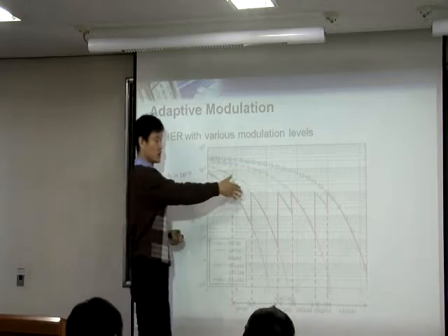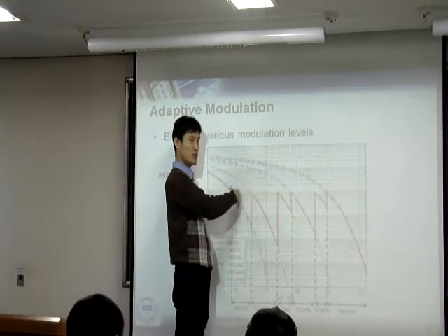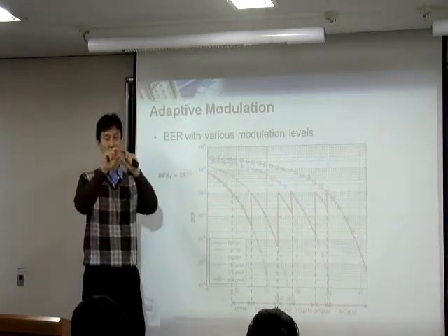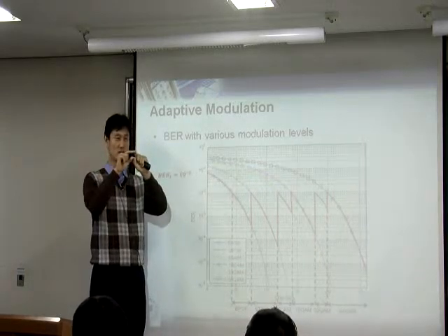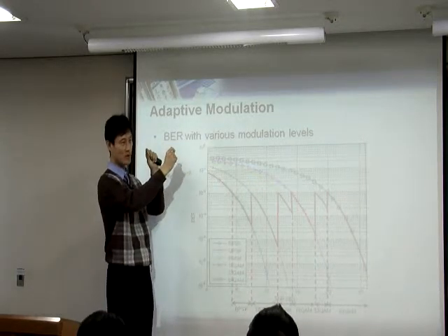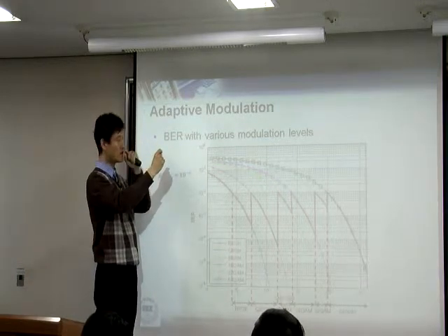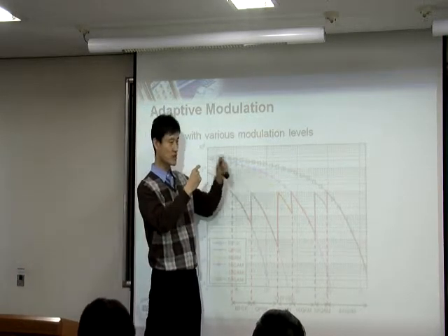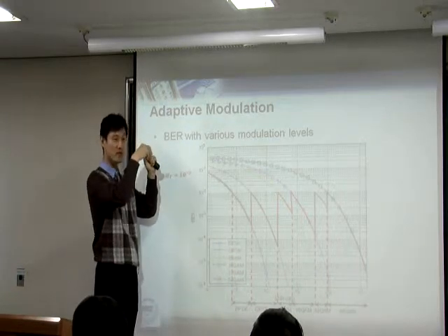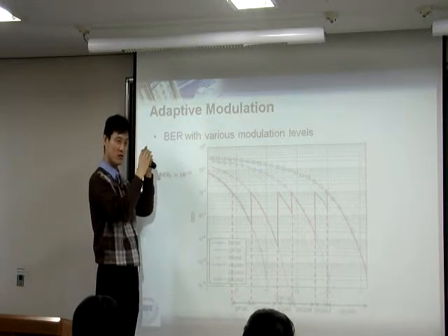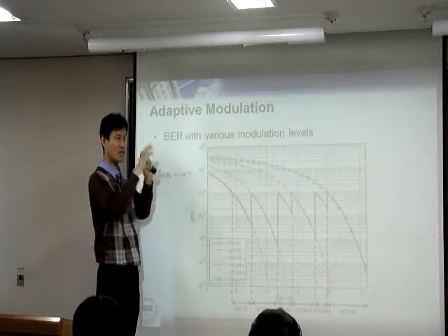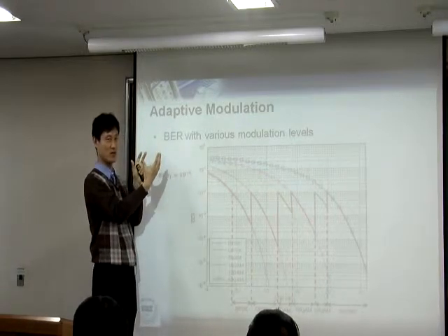No matter which one you use, regardless of which modulation you use, we're going to transmit one symbol anyway, right? We're going to use symbol by symbol transmission. We have one symbol, but sometimes if the channel is in good condition, we're going to contain more bits in that container. A symbol is just one container. We are not changing the size of the symbol, right?